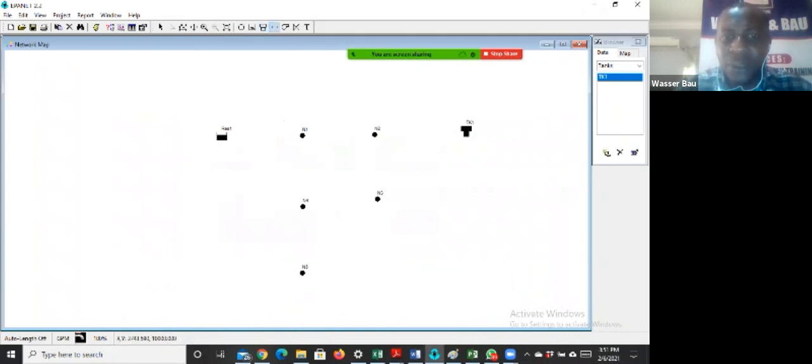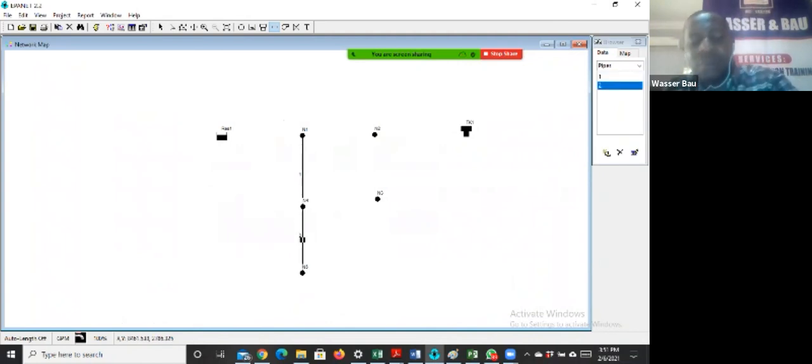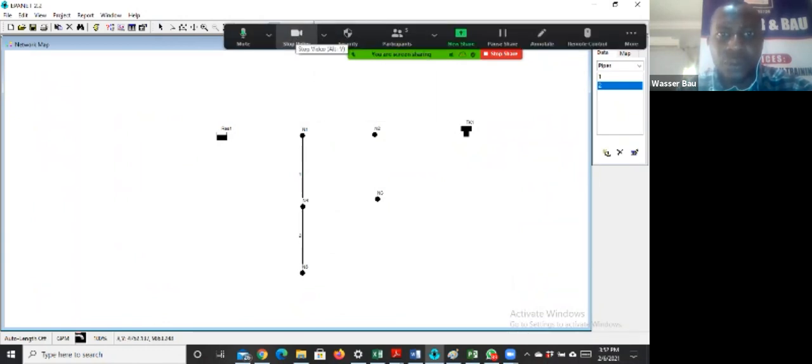So I'll click on pipes. I'll click on this pipe and click here. Once it does like this, you know it's okay. I'll click again, it will turn to a pencil. I'll click at the middle and it will go off, but the command will still be active. When I finish drawing, I'll click this select symbol, but I've not finished drawing. So the next thing I need to do is draw this other one.